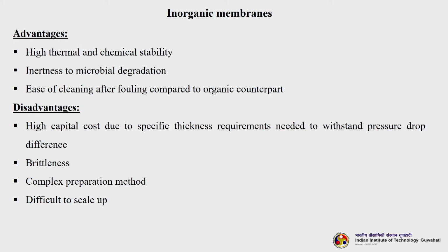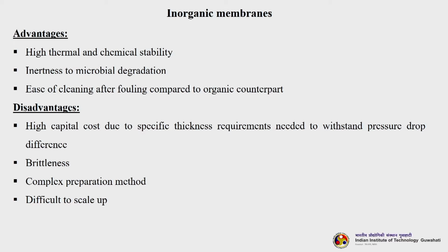So, the advantages and disadvantages of inorganic membranes. The advantages, which we have discussed earlier, are high thermal and chemical stability and inertness to microbial degradation. Cleaning is very easily done, because fouling is less compared to the organic counterpart, our polymeric membranes, which are more attached to the surface by virtue of the charges; here it can be cleaned easily. The disadvantage is high capital cost due to specific thickness requirements needed to withstand high pressure drop difference. Cost is always a matter when you talk about inorganic membranes. Brittleness is another problem, along with complex preparation methods and difficulty in scaling up. These are a few of the disadvantages associated with inorganic membranes.